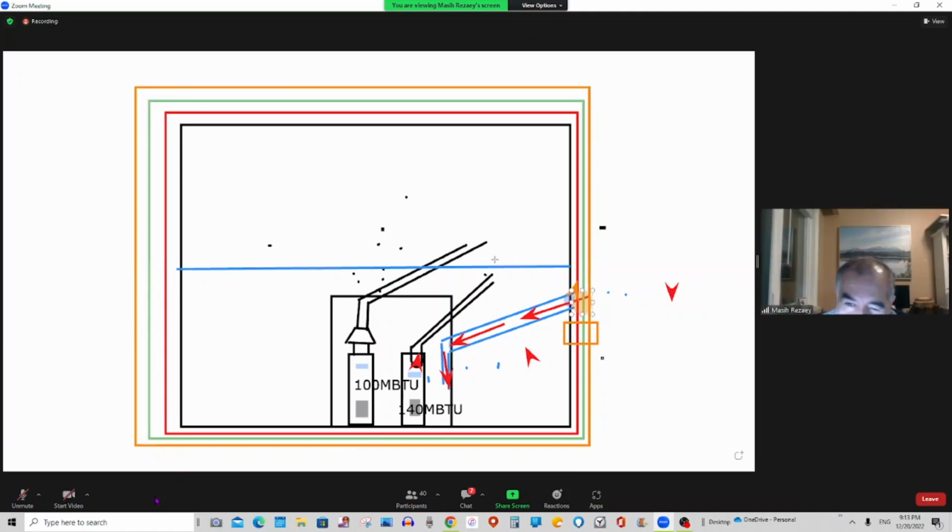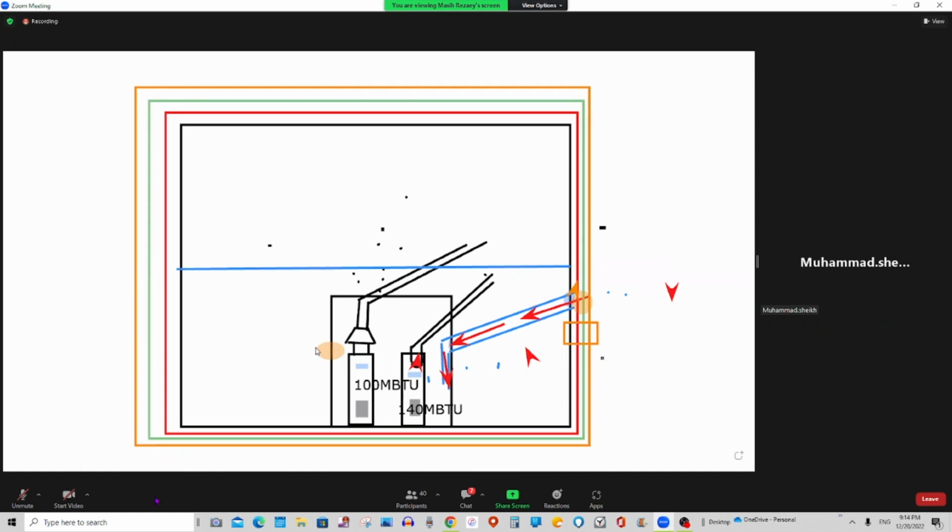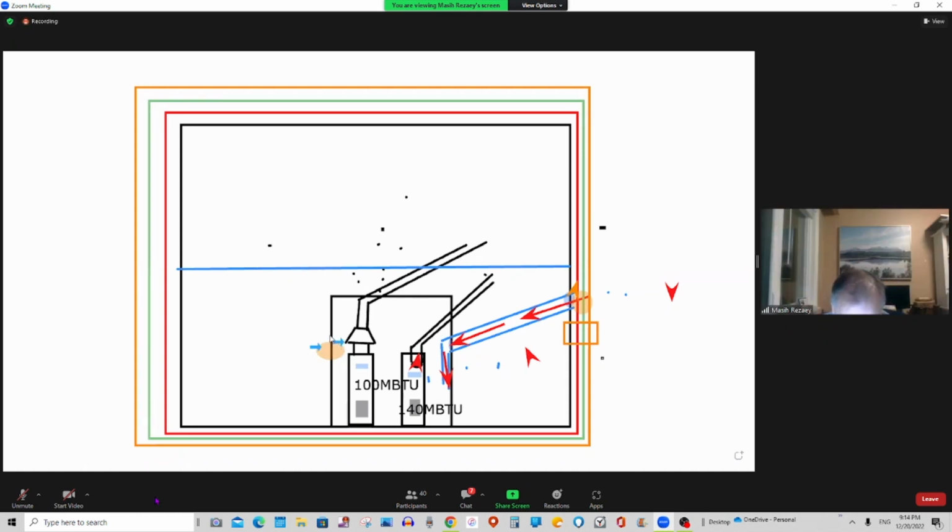Mr. Muhammad Ali, yes, listen, sir. First, you go to table 8.1, and only those appliances with draft control. It means only this one. You look at only that one, it has a draft control. You look at this one on table 8.1, you get 14 and 4: 14 square and 4 round. Then you add them together, 100 plus 140, and go to table 8.2.